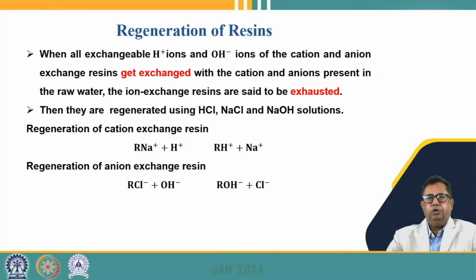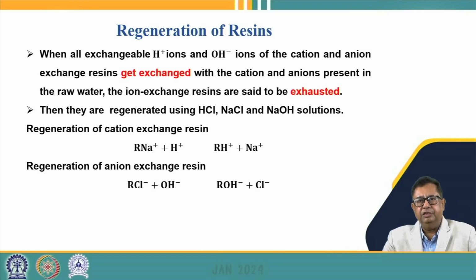So now we go on to the regeneration of the resins. When all the exchangeable H plus ions or OH minus ions in the cation exchange or anion exchange resins get exchanged with the cations and anions of interest present in the raw water, then the ion exchange resins are said to be exhausted.